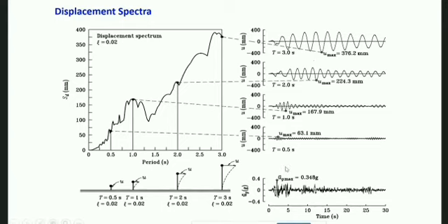You see that this is tried for a given earthquake data. So this data is the ground acceleration, a real ground acceleration. Then you see, when it is 0.5 second, the system has a period of 0.5 second. That means if this stick denotes the stiffness, then its stiffness will be 3EI over L cube. So for a small value of the period T, this stick will be short. For a larger value of period T, this will be longer. For a further larger value, this will be longer still.